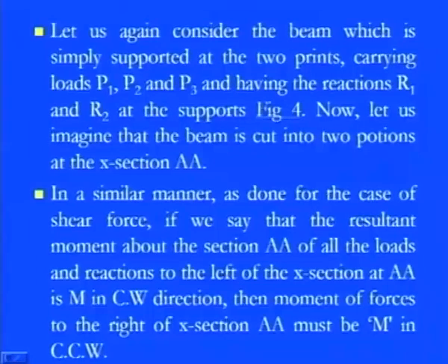And now you see here we found that for the reactions in the left section, the overall impact is coming in the clockwise direction. You see this part. Whatever the tendency of the beam is, it will tend to move in a clockwise direction. Similarly, we want to keep this particular beam in equilibrium. So what will happen is that a complementary bending moment will be formed in the other section to make the beam equilibrium. Automatically, on the other side the bending moment will be generated because of the application of force, and this will have the same magnitude but in the counterclockwise direction.